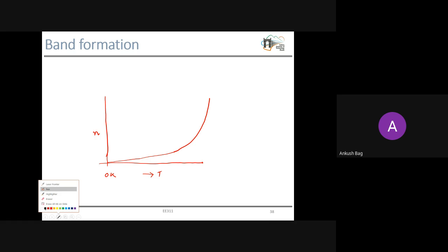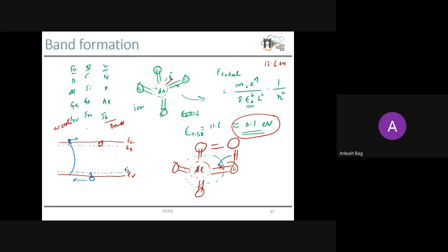Now the next point is how the carrier concentration will change with the change of temperature in a doped semiconductor. To understand this, let us take the help of this particular diagram. Suppose our semiconductor is n-type doped, let's say silicon doped with arsenic. With the arsenic, this silicon becomes n-type, that means arsenic has a 5th electron, which it will contribute as a carrier.